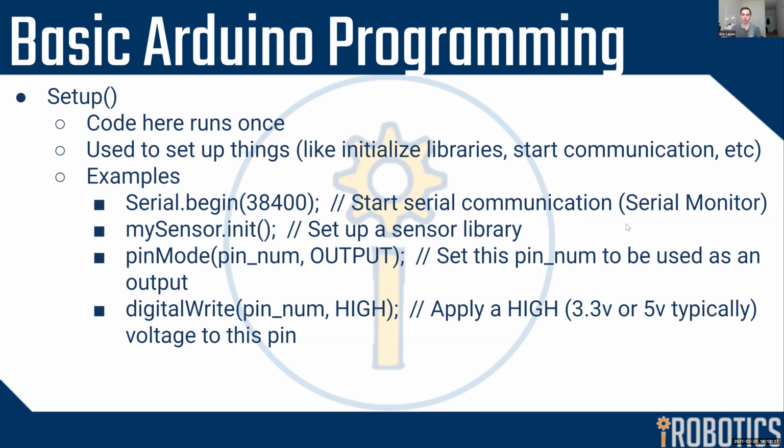I would just recommend generally describing it, but you don't need to do it for every single pin, just ones you want to be a logic 0 or a 1, 5 volts, 3 volts, 0 volts, whatever it is. But if you're doing communication, the pins for I2C or for serial, you don't need to tell it. There's no pin mode serial or something.